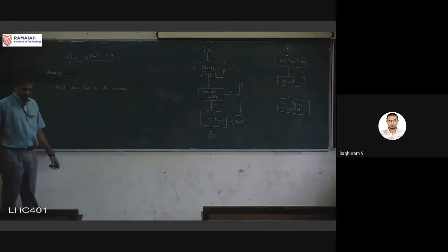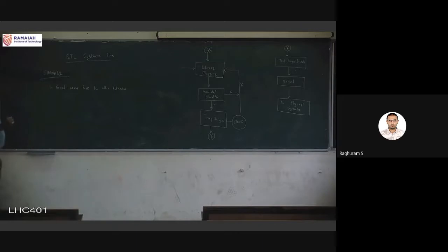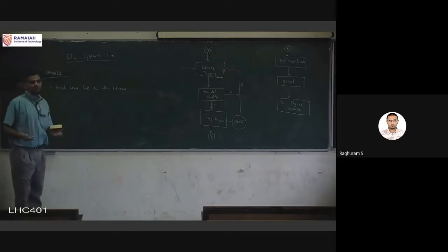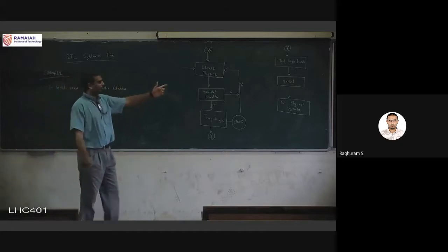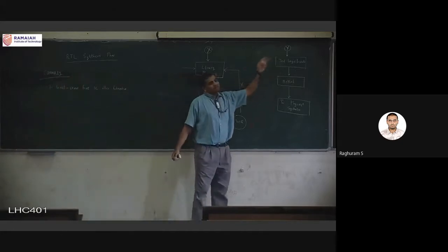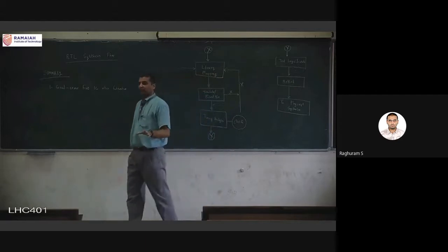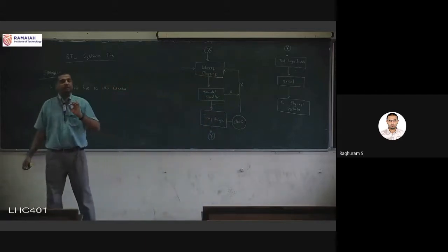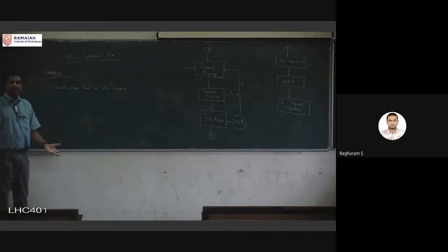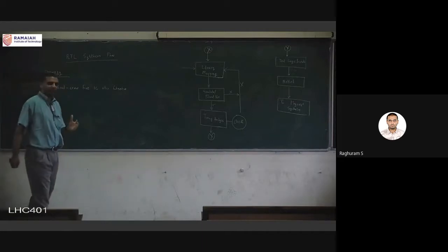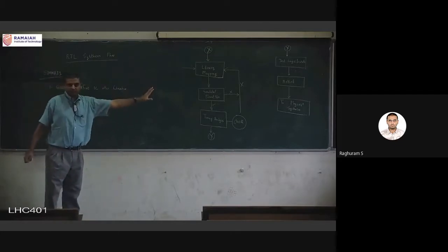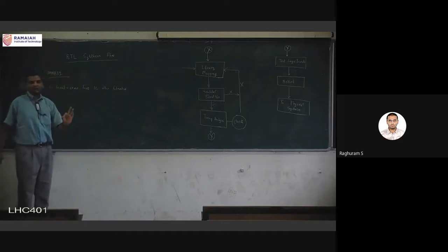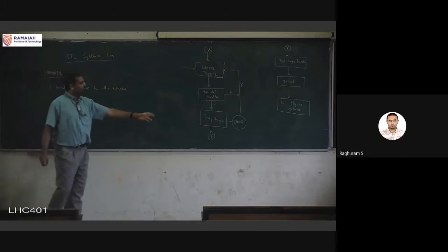So one single goal, if I can say, what is the goal of this type of flow? The one single goal is there should be no errors. Now we don't want to get confused between this and test logic insertion. This is a completely different aspect that we are checking. That is checking for errors that are induced by the fabrication process. Fabrication process is also not perfect. There might be some errors there, but in this flow we are not looking at that. We are looking at functionality, timing, power of the final netlist.